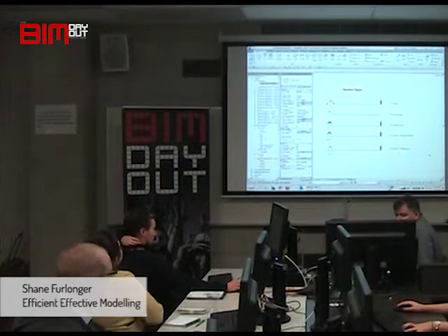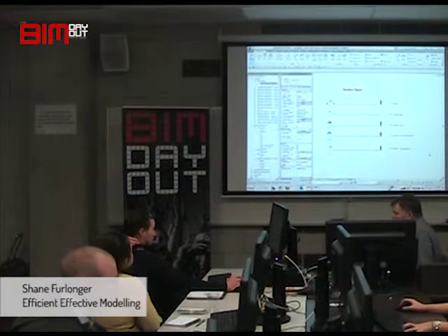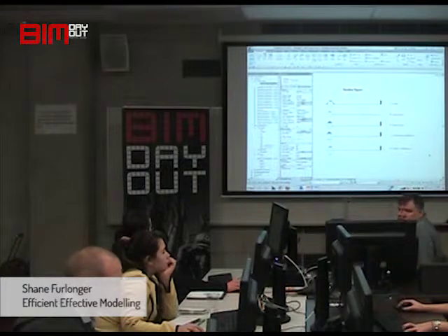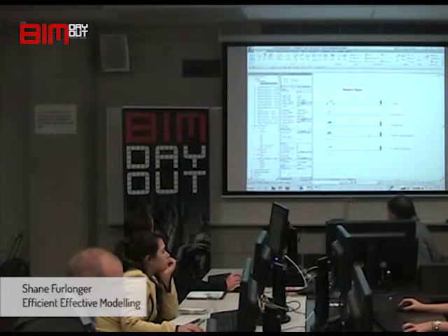So if you're modelling and you're doing a heap of sections through something because you want to see how it looks at a certain point in time, you can use these temporary section markers here, and they stand out really well because they're nice and square compared to all the ones you would normally use for documentation.